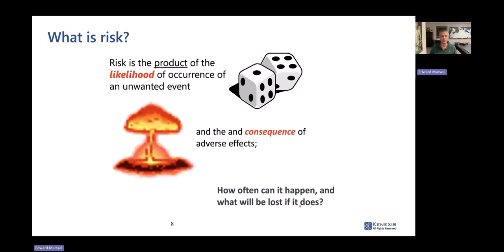Instead, what we wanted to do was allow you to have the flexibility you need to select that target yourself based on, basically, the risk, the likelihood that something is going to go wrong, and the consequences if it does go wrong. We're going to allow you to calculate that risk and then design your SIS so that it provides the appropriate amount of risk reduction.